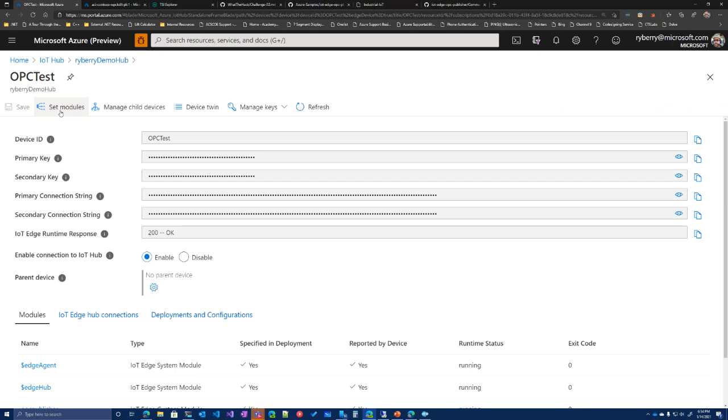So hopefully that provided everybody with a good overview of how to get data from pieces of equipment you have on a plant floor using an Edge device and the Industrial IoT modules that I posted a link to. And I talked about a couple of different ways that you can simulate data if you don't have a programmable logic controller that you want to interface with directly right now, or maybe your security team has some restrictions over what you're able to connect to, and you have to simulate it to show how you can devise some interesting ideas of what you can do with that data as it gets posted to the cloud.